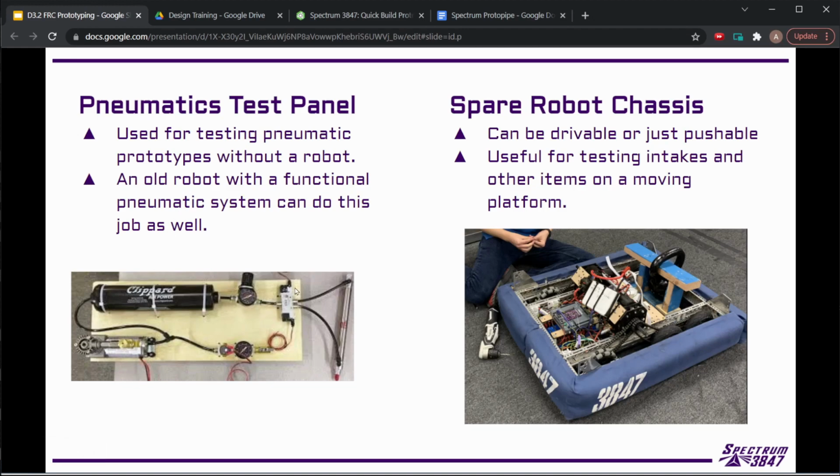There are little buttons on some of the solenoids, so it's relatively easy to push them in, and you can swap which air it is. So if you have some mechanism that is going to be pneumatic powered on the robot, you can build a prototype with it and use the pneumatics to actuate it in the exact same way that's going to be done on the robot. And so hopefully you can learn in as much detail about how the cylinder mounting locations are going to work and anything else that we're trying to test.